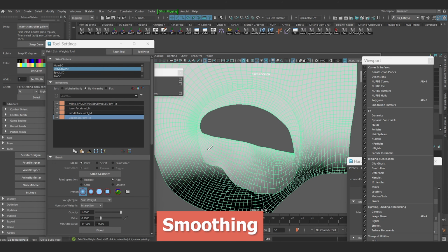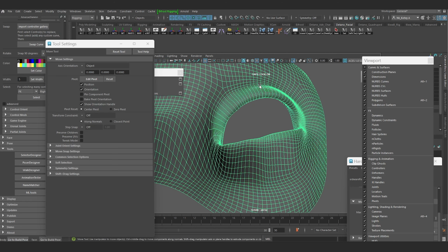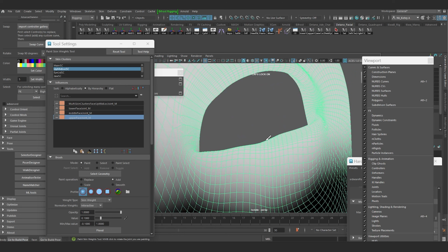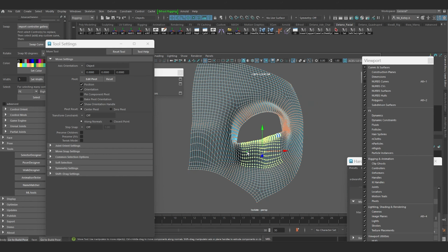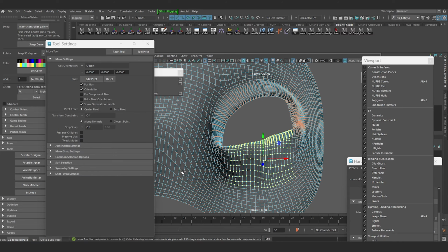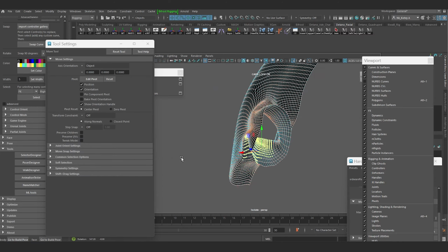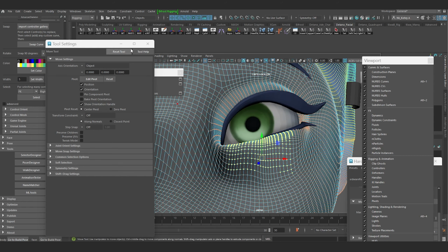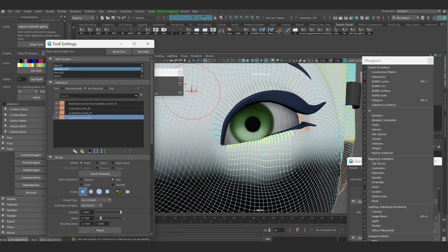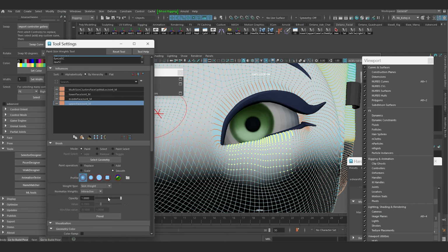And now, just to get something a little bit more refined, I'm going to grab a few points here and do a smooth flooding of just this region, the more important region right there. Let me deselect some of these, just so the inside part starts to look a little bit better. And I'll just go into my weight paint tool and just go smooth and just start flooding.